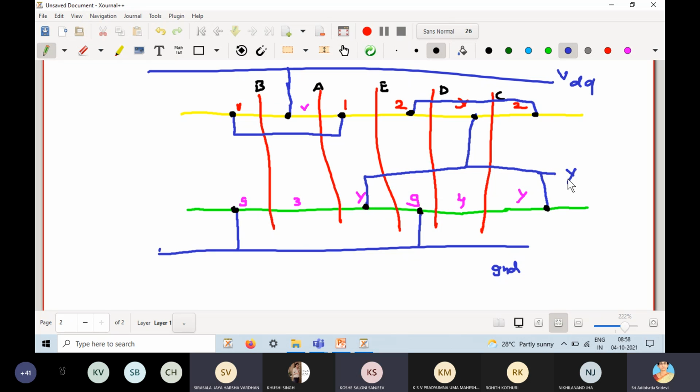Yes, ma'am. So this is how we draw the stick diagrams by using Euler path. You see here, just for a 2-input NOR gate itself, we have extra contacts and wires in our normal, direct way. But if you use Euler path, even though it's a complicated function of 5 variables, we could make it without any additional contacts, just with very minimal metal contacts. Do you understand this? Yes, ma'am.